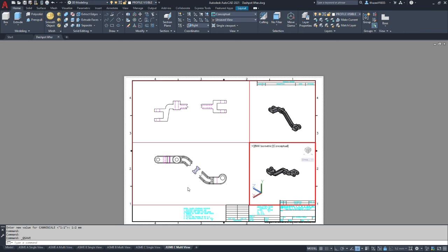They're not exactly perfect, but make sure you're following your checklist and observing all the ISO and ASME checklists. Don't forget to change your fillet sizes, and this is a metric drawing, so you need to change it from inch to metric, so don't forget those things. And as always, I'm going to harp on you to leave some space here for the revision block. That's going to be something that when you go to an employer is going to be a flag that you're a newbie.